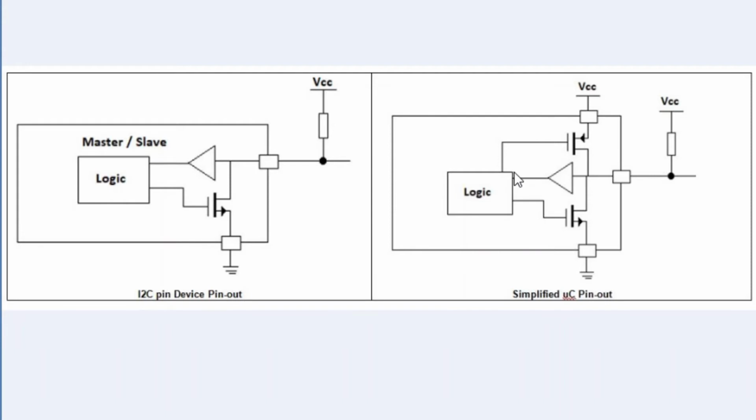Now, if we switched it to a high, we would pull that up and effectively short out that. And that doesn't meet the requirements of being open drain or open collector. But what we can do is we can switch it to an input. And by switching it to an input, effectively we disconnect these two FETs from the circuit, and effectively we have a high impedance because it's an input. So when we switch to an input, there will be no more current flowing in here, so that resistor will pull the pin high. And we achieve that.